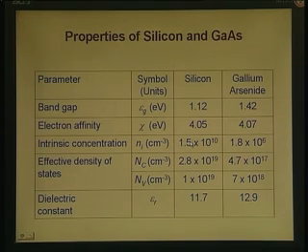But the formula is very important, because now what you can do is you can use this value of Ni for room temperature. So these values that are being shown are valid at room temperature, temperature is 300 K. So normally if it is not indicated, you must take this value as 300 K. So you can use this value of Ni at T equal to 300 K, and then you can use the formula to find out the value at any other temperature. So that is the way you must calculate the concentration at any other temperature.